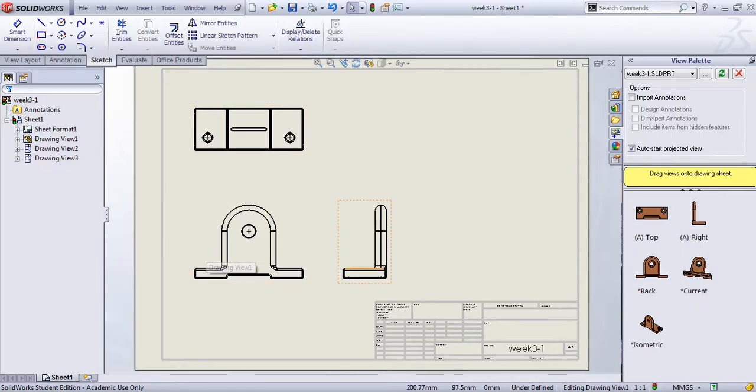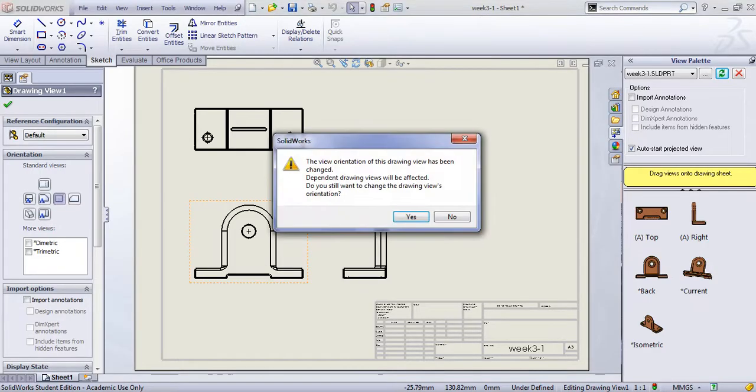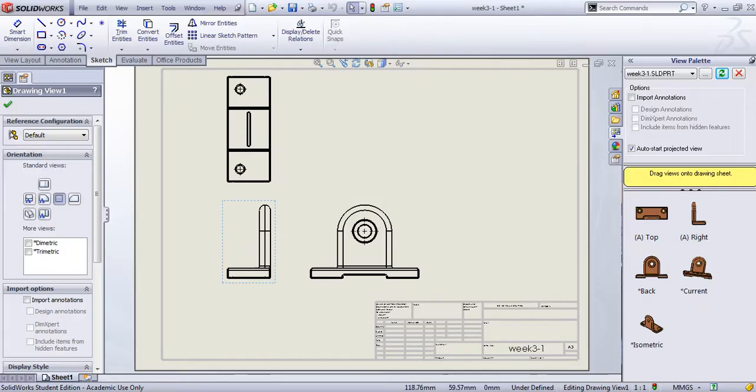You have other available views, and if you miss some of them after using or deleting, and you want to get them back, you go and click here, and it brings back whatever is remaining by this refresh. Let's click on the front view, and then of course here you can change your front view. If this is the front, but you want, instead of front, left, this is how it looks like here.